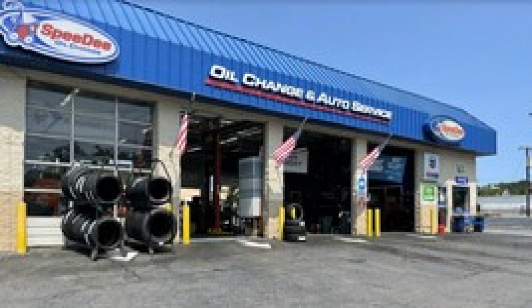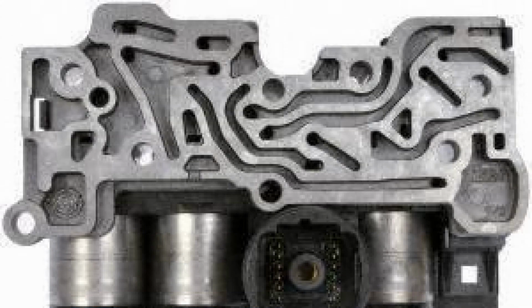Diagnosing and solving problems. Always check the technical service bulletins, TSB, for your particular vehicle first. Problem P07A6 may already be a known problem with a known fix issued by the manufacturer. This can save you time and money during diagnosis. The next step is to visually inspect the connectors and cables for the gearbox. Look for scratches, abrasions, exposed wires, burn marks or melted plastic. Using a diagnostic tool, clear the fault codes from the memory and see if error P07A6 returns.